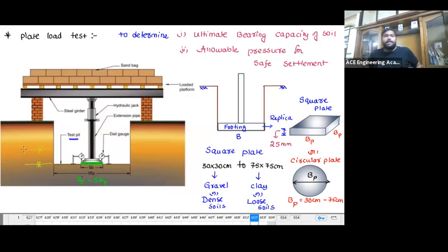So there are dewatering methods. You might have heard about the dewatering techniques in hydrology also. Anyways, for ESC there is one separate topic also. We'll discuss it at the end. So by using the dewatering techniques, you are going to lower down the water table by at least 1 meter below the plate level.